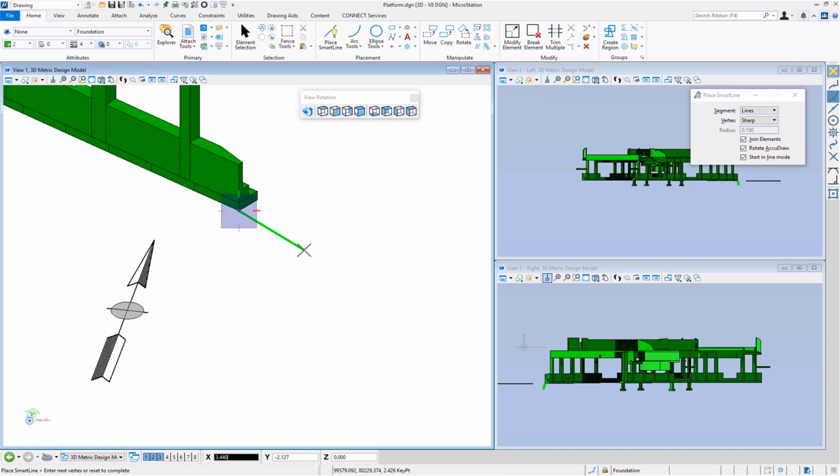This is X and Y, and the compass will tell me that because it shows up as a square. If I wanted to do distance and angle, or what we call polar, I would switch by hitting the letter M, and this would switch my compass from X and Y, or rectangular, to polar, distance and angle. And you can see this reflected down on the Accudraw window. I'm going to hit the letter M again and go back to rectangular.